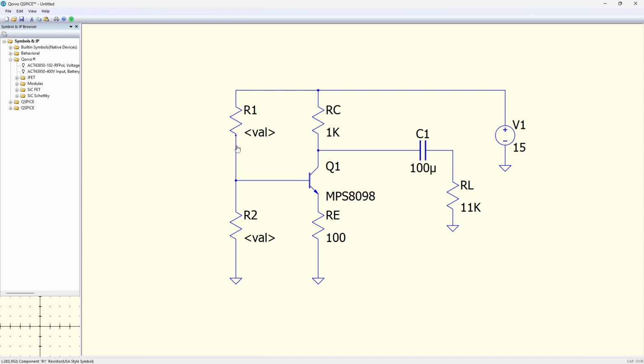And you could change these resistor values a great deal and have almost no change in this voltage. And that would mean that you'd have a hard time getting exactly what bias you want. Adding some resistance in here kind of gives a cushion so that there's some voltage across RE, and then your values of R1 and R2 can be less precise and still give you the correct range and operating point that you're looking for.